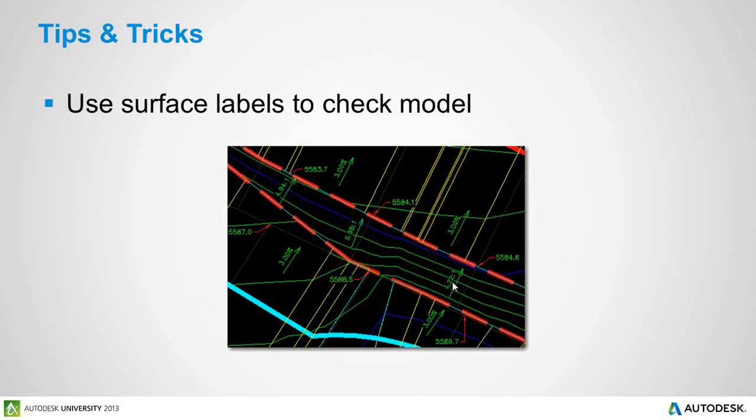Well, I need to make sure that my slopes here do not exceed my design criteria. In this case I had a 4:1 maximum slope, and you'll see all of these are flatter than that. I got 4:1, 5:1, so there's nothing steeper than the 4:1 value in this image. So it's a great tool. You can grip edit these, move them along, drag them, and get real-time feedback on how your model's behaving. All right, so that's the 5,000-foot view.